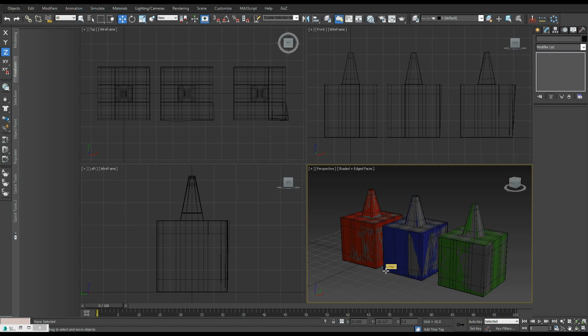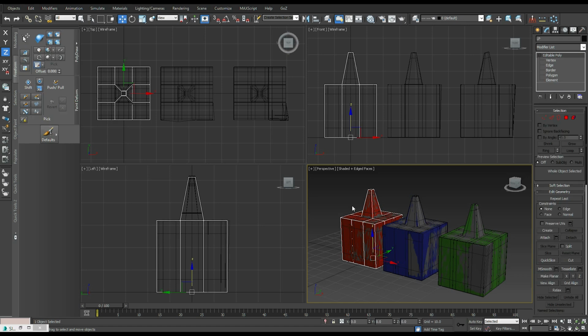The first thing I want to talk about is how important it is to line up the low and high poly mesh. This might be something some people kind of overlook or don't put as much emphasis on as you could, but it's absolutely critical that you line up the low and high poly as close as possible. So it's kind of like a balancing act between how much geometry should I have in my low poly, and how much time should I spend lining all this stuff up to make sure it gives you a proper bake.